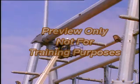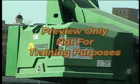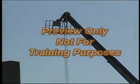Make sure the load is balanced. Always check the loading prior to operating the lift. A manufacturer's load plate is attached to the lift. Never use a lift as a crane unless the manufacturer has designed it to lift loads in such a manner.